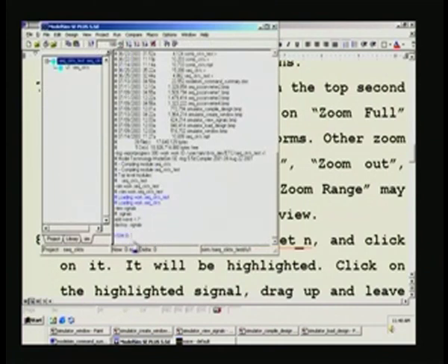You can either key in the command as I mentioned, or it is all menu driven, and you can use run here. You can also notice 100 written here. It is called run length, and you can change it if you want. Let us say if I click on the top arrow here, it has advanced to 110 nanoseconds. Just follow my words, that is enough. If I click on the lower one, it has come back to 100 nanoseconds. It can go down, so in how many units it has to go up or down, you can program that also.